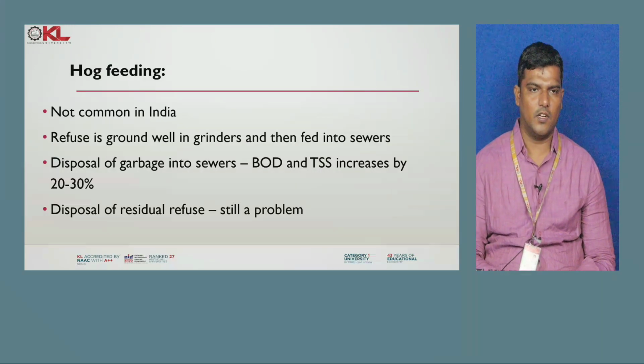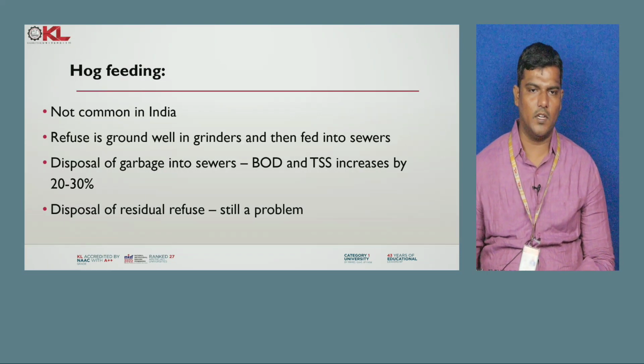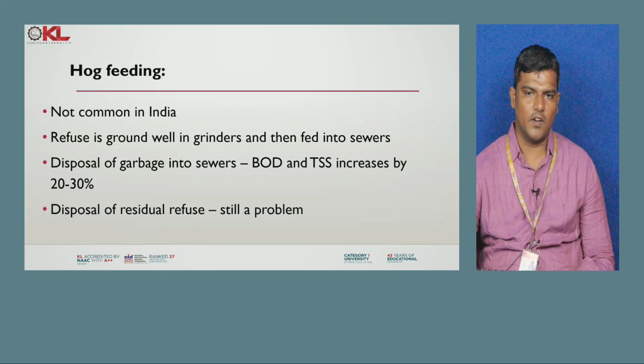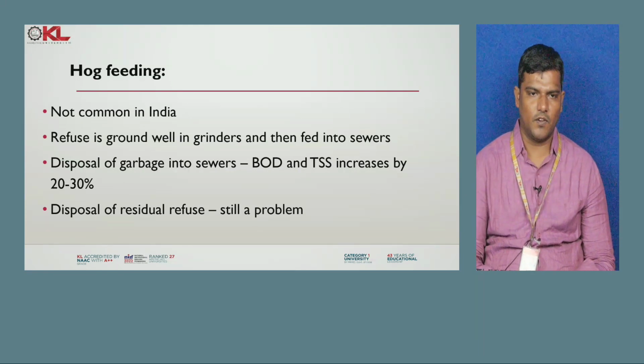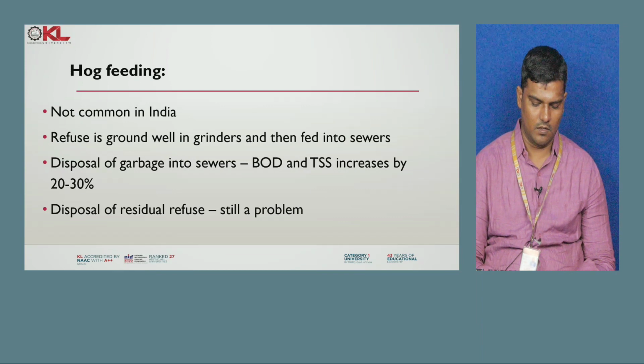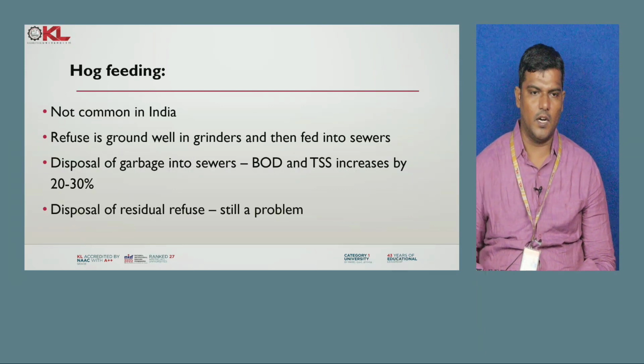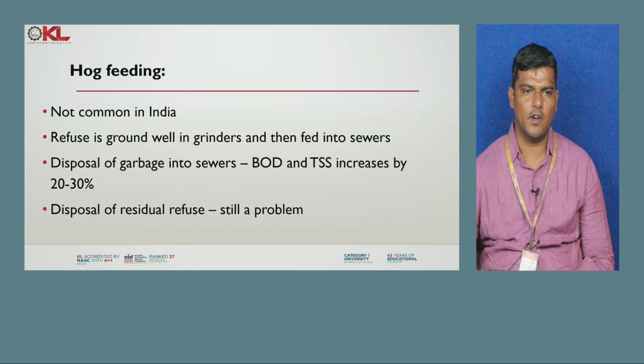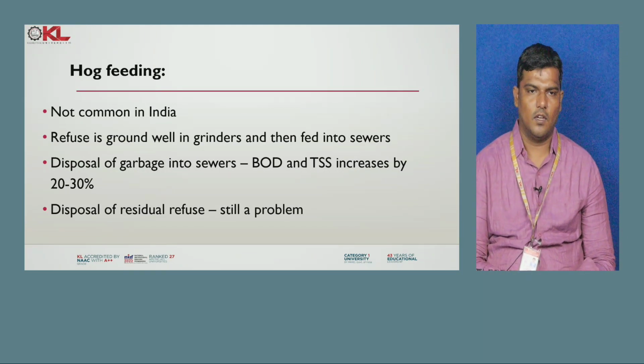Coming to the last one, that is hog feeding, which is not common in India. Refuse is ground well in grinders and then fed into the sewers. With disposal of garbage into sewers, BOD and TSS increase by 20 to 30%. Disposal of residual refuse is still a problem. So that's why hog feeding is not preferable in India.